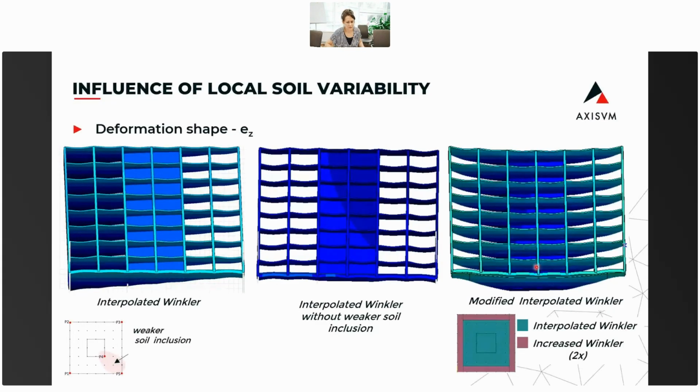It contains the effect of the local weaker zone and also the increased edge stiffnesses. Yes. This example shows us how the interpolated Winkler model can help identify the governing mechanism, and it also demonstrates that with an appropriate adjustment, it may provide a practical approximation of actual soil behavior while maintaining the efficiency of the Winkler-based approach.